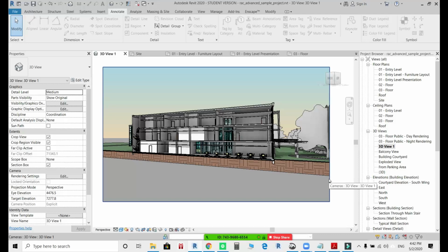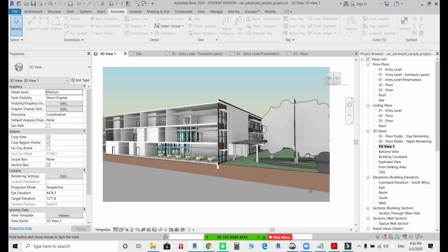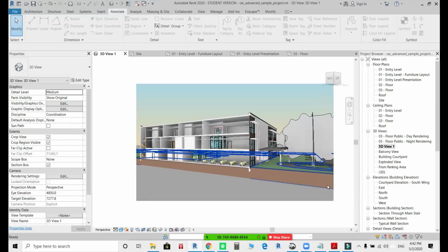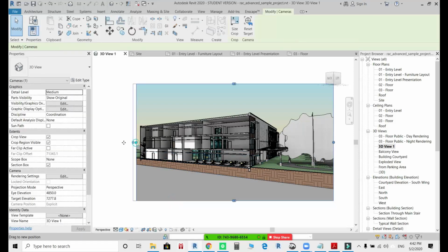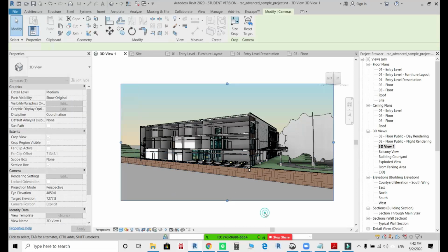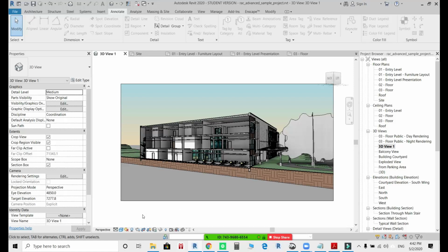Yeah, this is it. Sorry, I have another question. Sure. If I want to be specific with the sun location, for example, if we are in London or in Greece, we have completely different angles of the sun. Is there any way to know where the building is and take the real coordinates of the sun? Yes, there is a possibility to do this, and there is an option here to turn on the sun path.